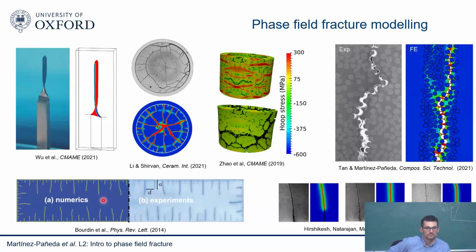If I start a simulation with no crack, will I still get a convergence solution? If you start with no crack and you start nucleating cracks later, yeah, this is the case here. So this one starts with no cracks. You do get, we'll say a few words about nucleation tomorrow, but you can nucleate a new crack, and it will get convergence, there's no problem. The nucleation part is not demanding convergence-wise, but this is a good point to discuss tomorrow. It has to be a minimal solution that has to exist for this corresponding solution. Yes, but you can find the global minima, yes.